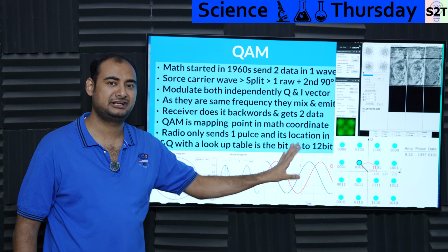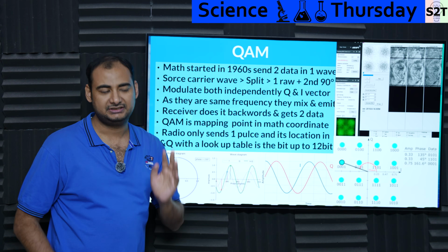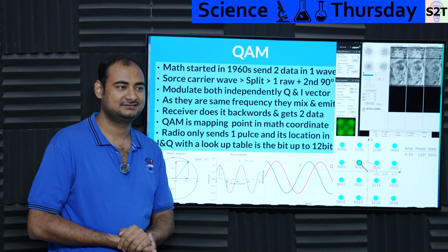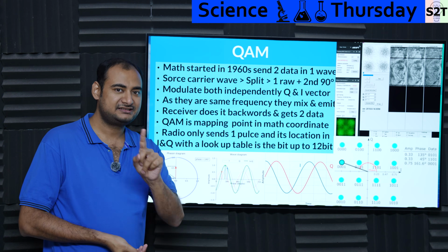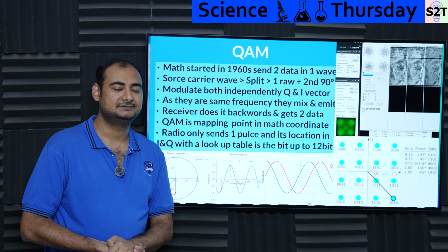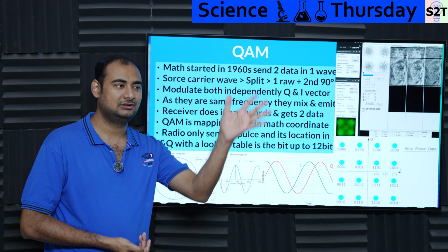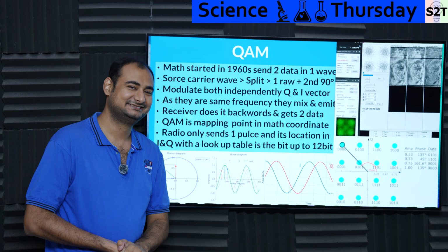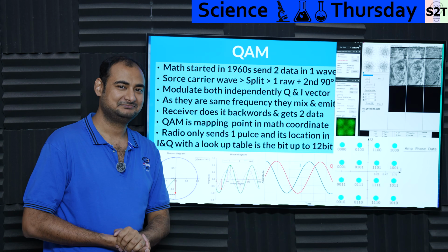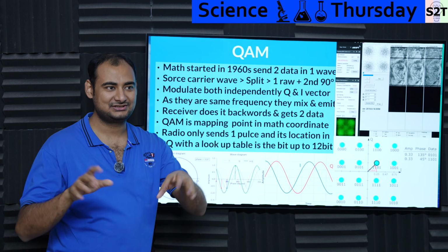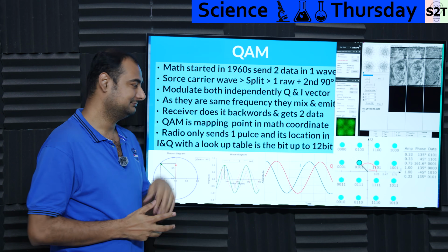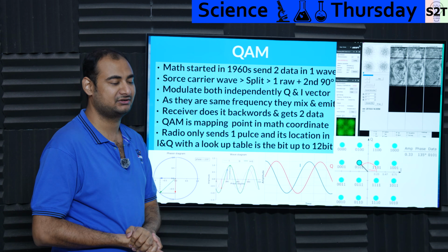And the highest coordinate map right now in use is 4096. Yes, there will be 4000 points there. How many bits is that? One symbol is 12 bits. Tick, 12 bits sent. It's literally sending more than 1 byte. Literally in one shot. Done, sir. Basically, 2 of those symbols will translate into 3 bytes of data, complete bytes. That's why you are achieving like 1 Gbps sort of speed.